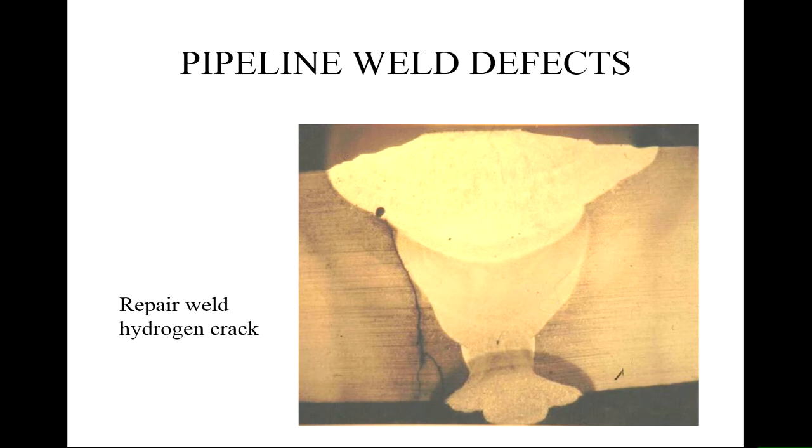So in most situations, the crack will tend to propagate in the heat affected zone. Now, that's very interesting, because the next topic will be repairs, and also repairs carried out to correct improper welds. Actually, these repairs might lead to catastrophic defects like hydrogen cracking. In this image, hydrogen cracking was caused by an improper repair weld.